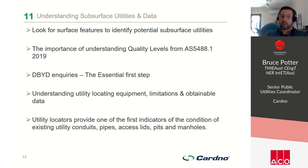You also need to understand the quality levels from AS 5488.1 2019. That standard talks about the 4 quality levels: quality level D, which is base level data, quality level C, quality level B, and quality level A. From quality level D all the way through to quality level A, you're increasing the level of accuracy and decreasing the amount of risk associated with that information.